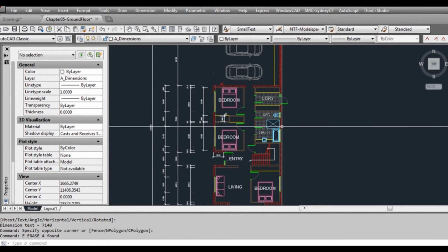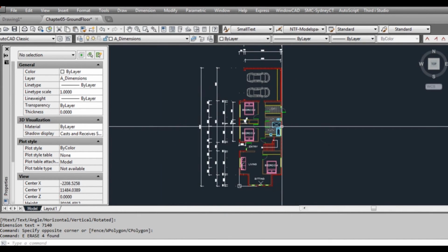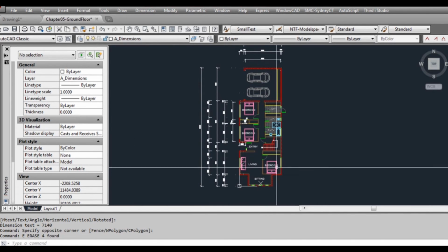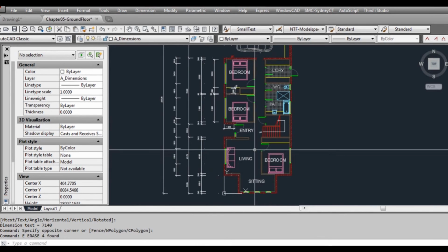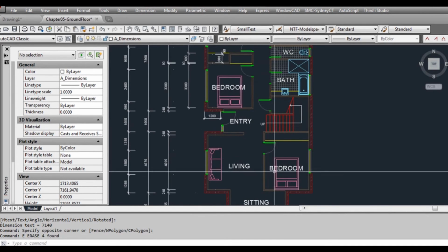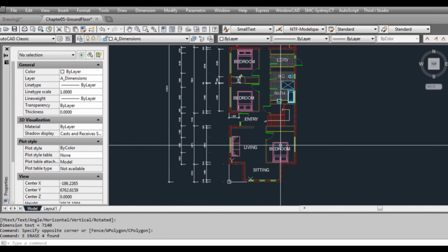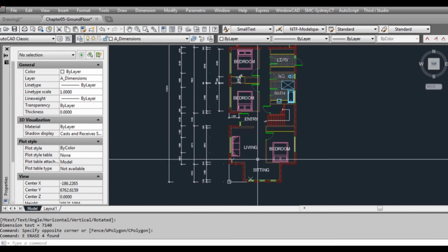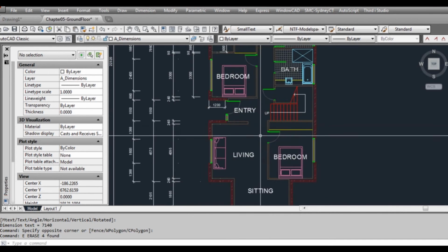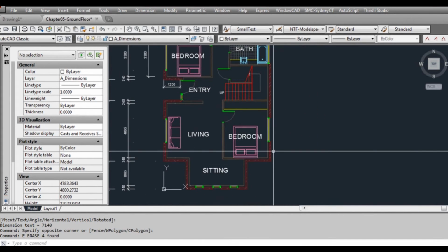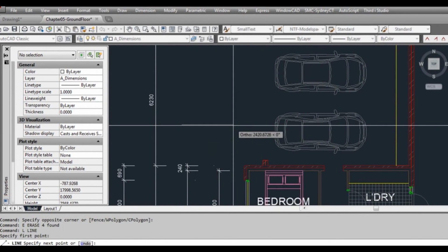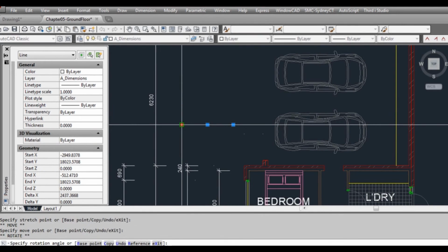In the sections, we may use other dimensions, such as the angular one. Sometimes I have had to use angular for floor plans where the walls might be angled, or the building's angled to the site boundary somewhat, so you need to let people know what the angle of that is. We'll just do that anyway. There's nothing specifically in here that's angled that we need to do, but what I'm going to draw is, I'm going to draw a line, and I'm going to rotate it 30 degrees.